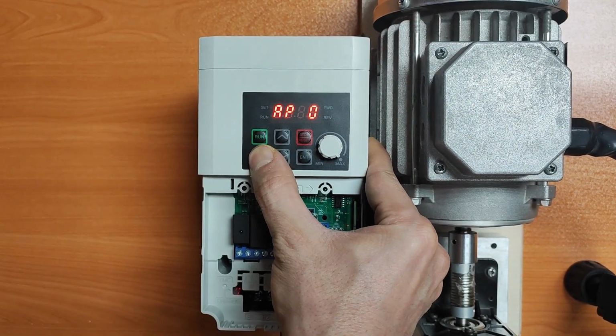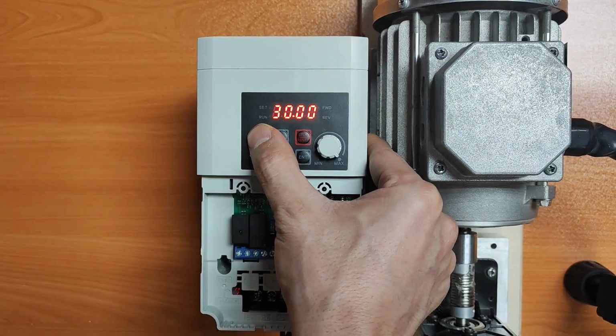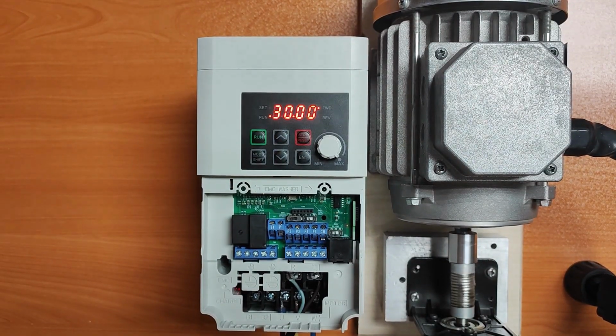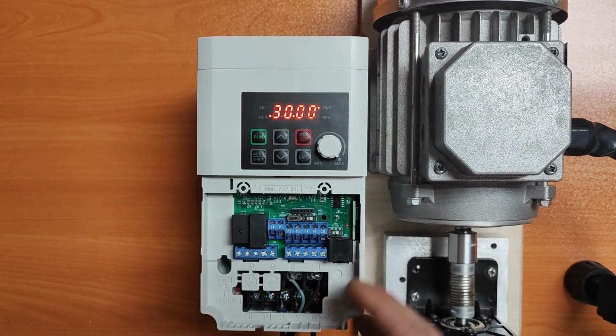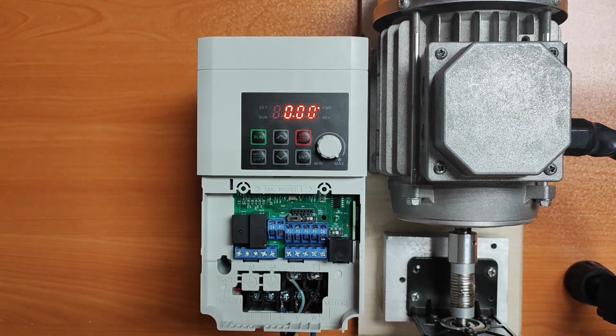Okay, I'll go back. Now I'll start the inverter. Now, if I stop the inverter, as soon as the frequency reaches 28 Hz, the inverter injects DC current into the winding and the motor stops instantly. Now, I'll stop the inverter. As soon as it hit 28 Hz, it held the motor shaft for 4 seconds and my motor locked.